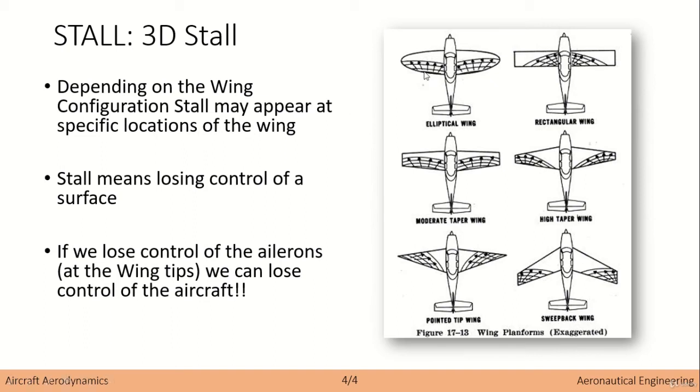And this may occur naturally, or it may occur due to an increase of the angle of attack. Okay, so you shouldn't just assume that it won't happen. It could happen, okay, even if you are at relatively low angles of attack, it may happen too. So as you can see, the elliptical wing is actually quite good. It performs well in this point, which means that it is distributed well around all the wing.